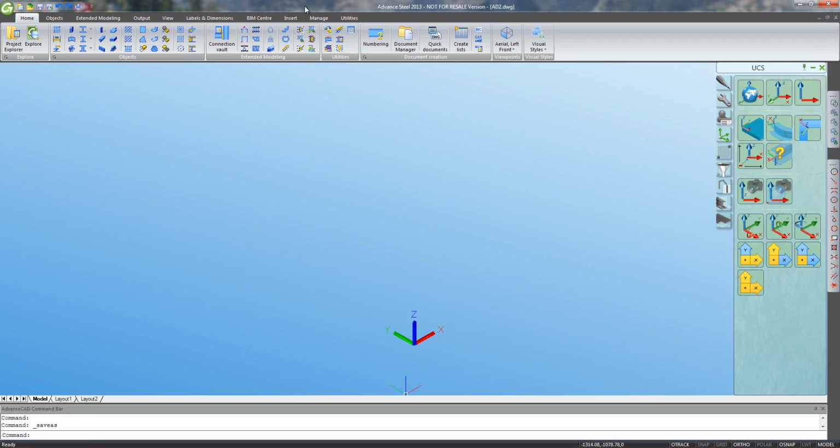Now we're ready to start modelling, so we'll put in our straight stair using our macro for a straight stair and simply enter a couple of 3D coordinates for the bottom and top of the nosing line, since we have nothing else in our model yet to snap to.